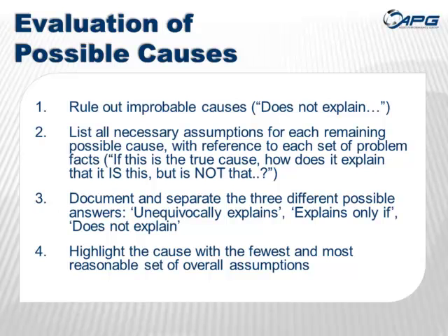The more specific the hypotheses that we develop, the more quickly we can evaluate them. So just quickly here, we're going to try to rule out the ones that simply don't make sense. And we do that on both sides of the problem description, the so-called is or is not. If it doesn't fit in one place, we rule it out very quickly. And so, for instance, I mentioned the defective dies. That simply doesn't explain the rough patch in the panel, so it's gone.